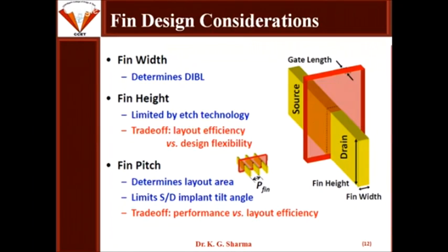Another thing is fin pitch. It is nothing but the distance between the 2 fins on the wafer. It is determined by the layout area and limits the source drain implant tilt angle. We'll discuss later on that this is also a problem: if a fin is there and we have to dope that fin with a particular dopant, the nearby fins are creating a hindrance, and there should again be a trade-off between performance versus layout efficiency.